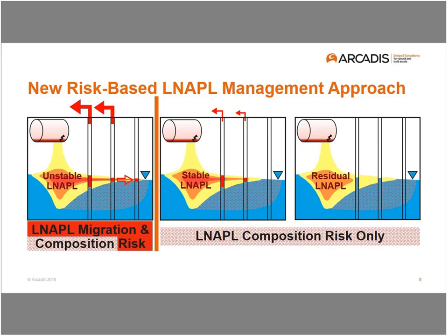Okay, so there's still oil in the pores of the soil, but it doesn't flow into wells. It's still creating, say, a benzene groundwater plume. So really, on these right two panels, the thing we're most concerned with is the composition risk. So there isn't a migration risk anymore. There's a composition risk that we might want to solve.